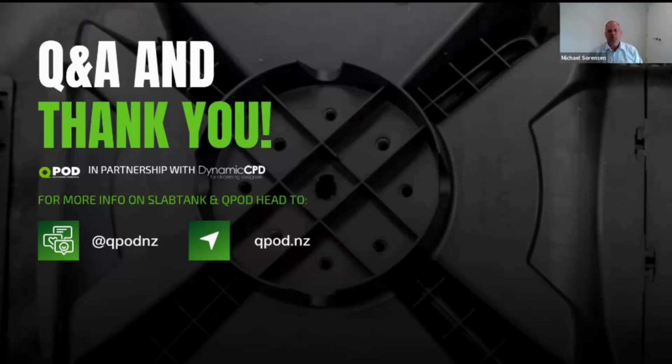Yeah, thanks, Peter. I just had one more comment as well on the last question about somebody putting a bolt through the top of the slab tank. As a designer, I wouldn't be too worried about that because that will be covered in concrete and it's never going to have any hydrostatic pressure on it because the tanks have an outlet at that level. So even anytime the tank fills up to the top, it will drain. It can't fill higher than that. So it's not ideal, but it's probably not going to be a showstopper.